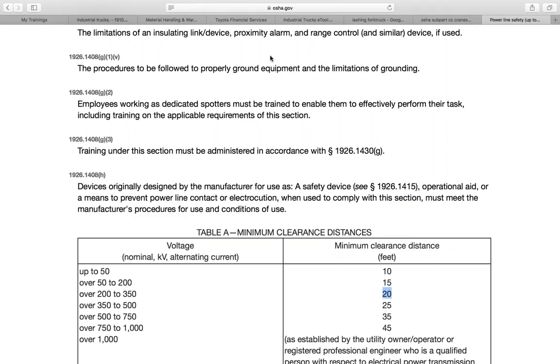And then ultimately, and last of all, we have to ensure that, like we said, the ground conditions can support the crane. Also, that we check that there's a safe path to move that crane around, and making sure that the crane can rotate, right? In the quadrants where the lift's going to be, and where all the outriggers are as well.